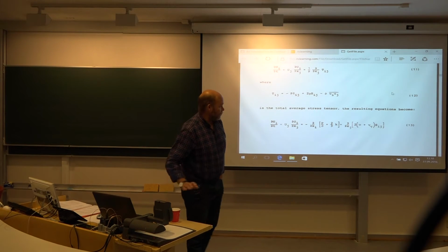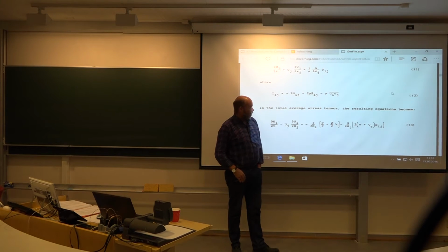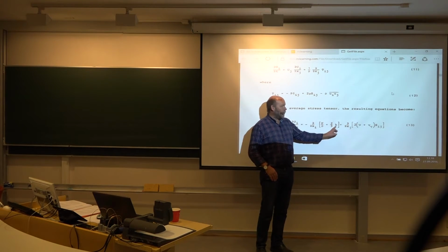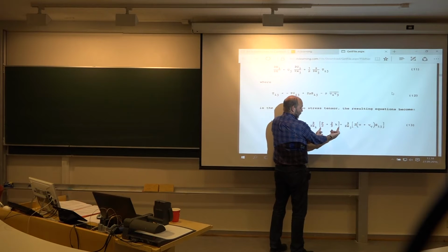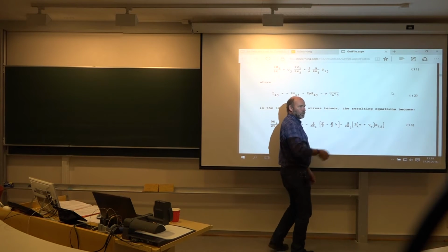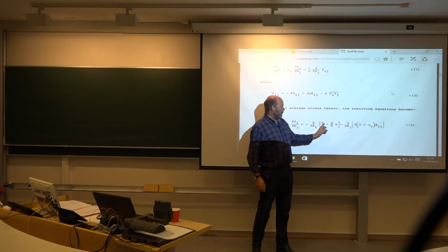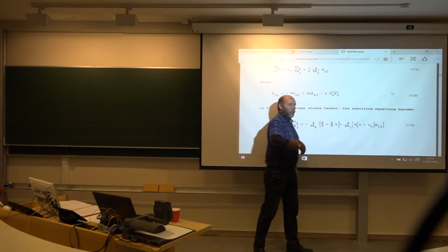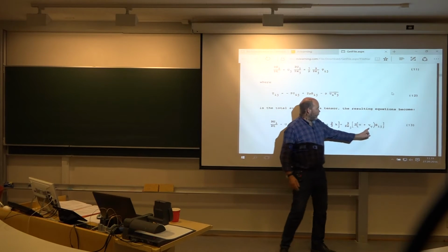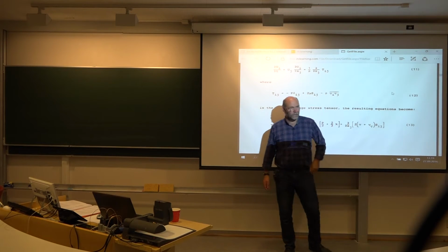Now let us construct a very simple turbulence model. I say that I forget about this K. I know he's there, turbulent kinetic energy, but I just call this square bracket my pressure, because I'm not interested in him, actually. I'm not interested in the pressure even. So I just call this entire square bracket the unknown pressure. Then I'm left with one single unknown function, viscosity.